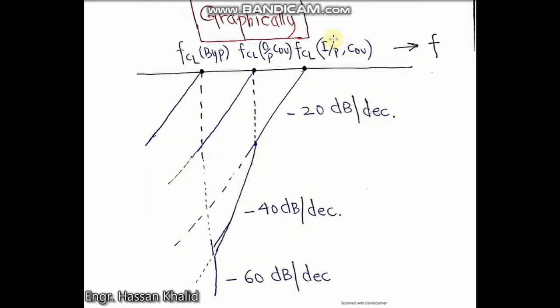Okay, now in the next point, we would like to arrange the 3 controlling capacitances: one is the input side capacitance, the output side, and the bypass capacitance, in the following way. This can be easily done by tracing the AC sweep graph in which you are changing the frequency, and then finding the points using the slope-intercept equation, or whatever you like to say, the total slope of the line. You will realize that in the first case it's minus 20 dB, and after the next transition it becomes minus 40 dB, and in the third, played by the bypass capacitor, it becomes minus 60 dB.